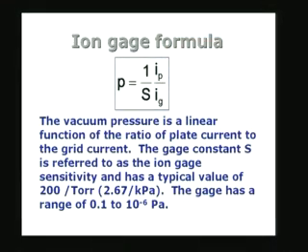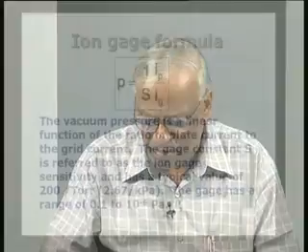During the first part, when the rough vacuum pump is on, you can use the Pirani gauge, which will be attached to the vacuum system, and it will show the minimum value after some time. After the pressure has come down to a sufficiently low value, the Pirani gauge will indicate almost 0. That means it cannot indicate anything sensitive, the sensitivity is very poor there. So, at that time the ion gauge will take over and give you the pressure. So, this is how it is going to operate.